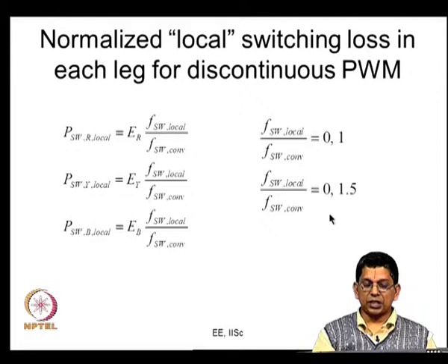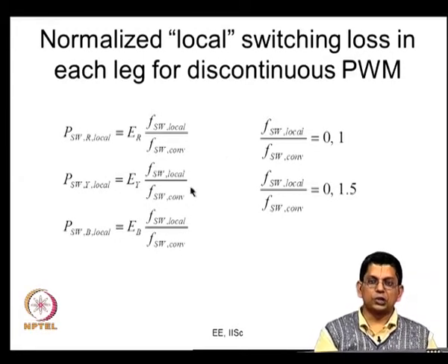So, the switching frequency of a particular device, if you look at it, is 3 kilohertz for 120 degree duration in a half cycle and 60 degree in another one. So, we can call the term average switching frequency. The average switching frequency is only 2 kilohertz now. The devices actually switch only 2000 times in a second, though the carrier frequency is 3 kilohertz. So, the average switching frequency is low.